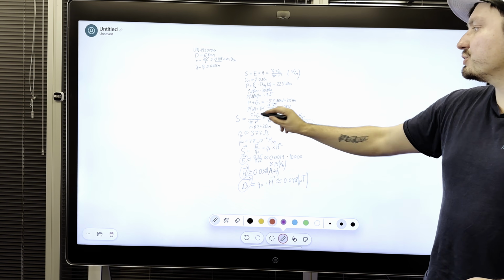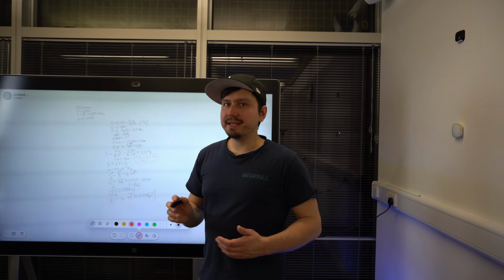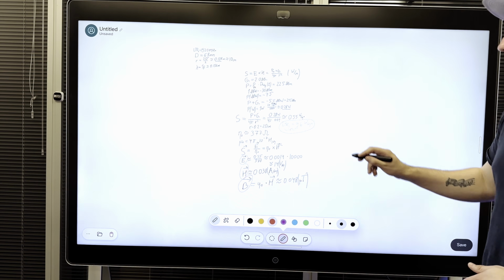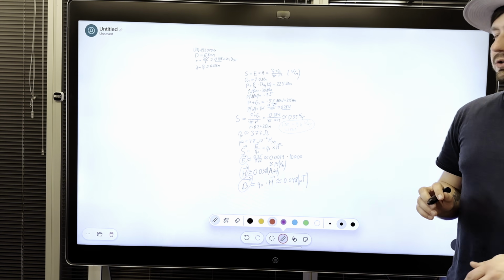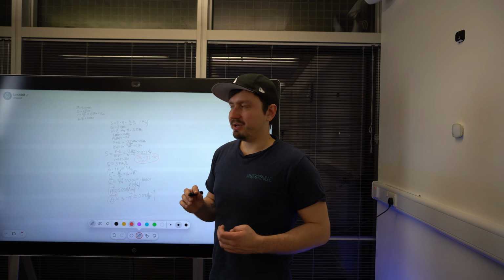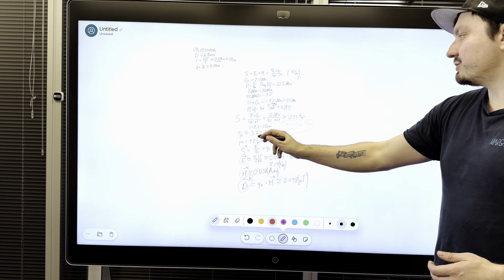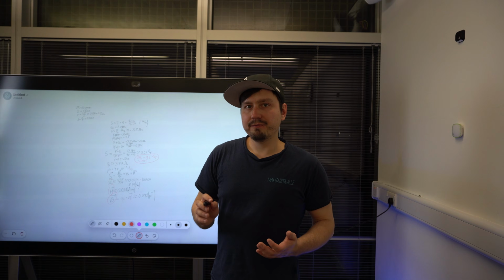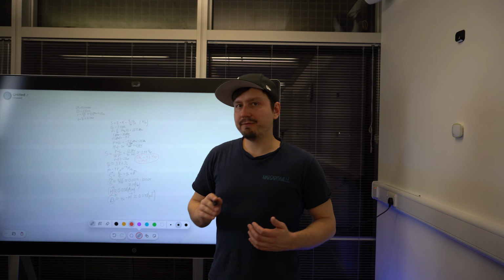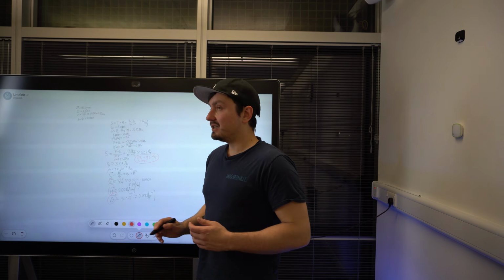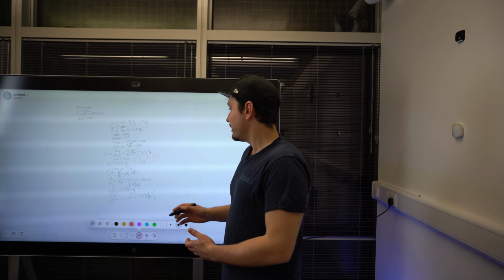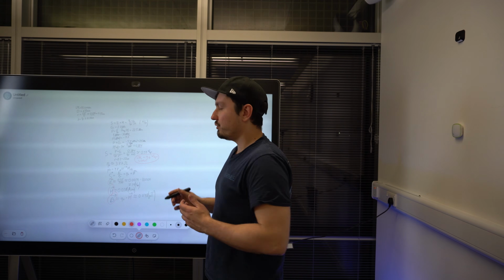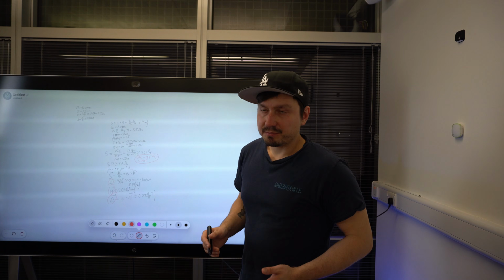And then we used the power density formula to obtain the value in watts per meter squared, which was below the ICNIRP limit. And based on that, we also were able to calculate electric field density, magnetic field density, and magnetic flux densities, which is all based on Maxwell's equations and constitutive relationships.